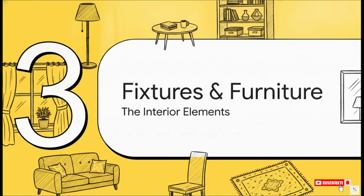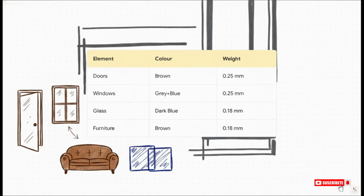That brings us to Section 3, fixtures, furniture, and glass, the interior elements. Now we transition to the functional elements. The stuff that turns a cold, empty concrete box into a warm, lived-in space. Notice how we start dropping down in line weight here. Doors and windows sit at a standard 0.25 millimeters, marked in brown and a gray-blue mix respectively.